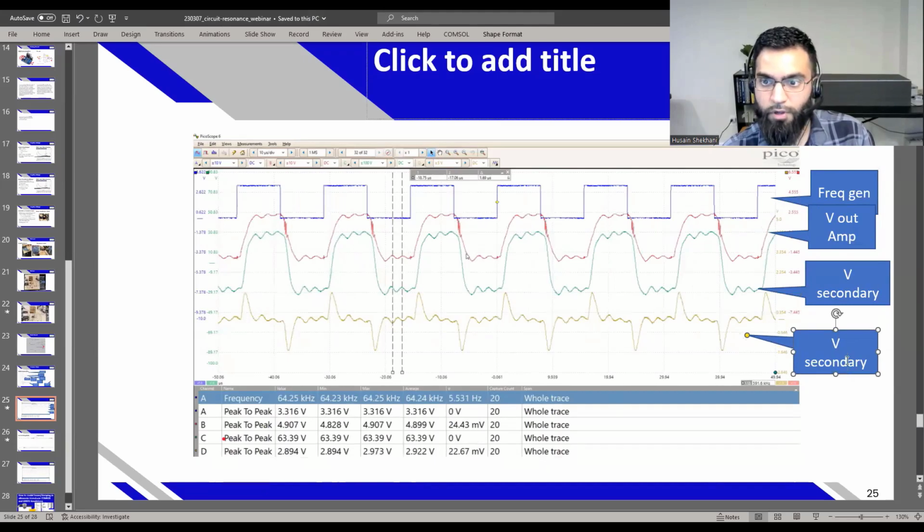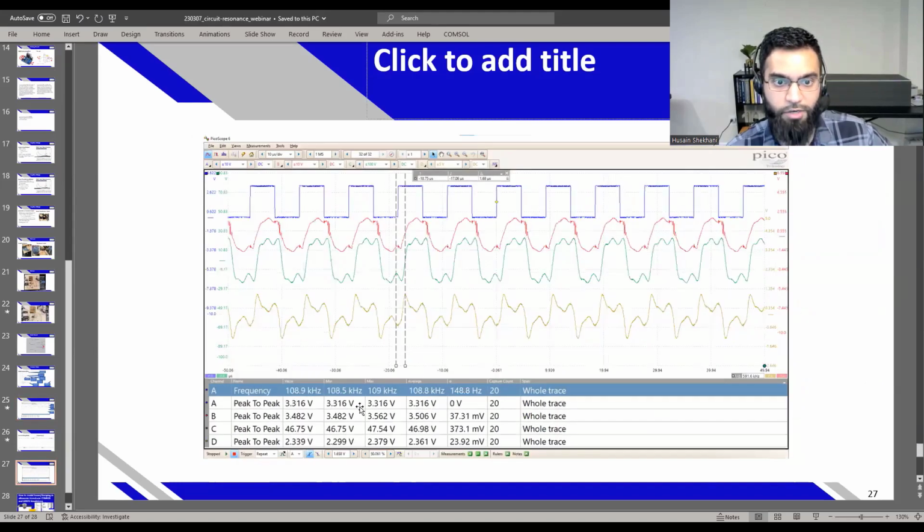So this is the voltage. This is the current, right? The second one is a current, or basically voltage over resistor. So you divide that by 10, and you get the actual current. Let me just skip ahead here. So this is during actual operation. This is the current waveform. This is voltage output. That's secondary. The red is input. The red is primary, and then the square. It's pretty logical in the order it goes.